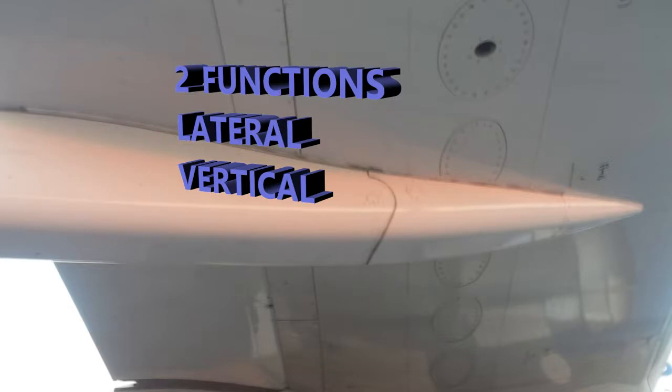Your flight spoilers, by the way, work in conjunction with the ailerons. It's kind of supplementary, but it still has an important function in conjunction with the aileron function. So you have inboard ailerons, your outboard ailerons, and then you have spoilers 3 to 7. So when it comes to roll, the spoilers involved are going to be spoiler pairs 3 to 7.